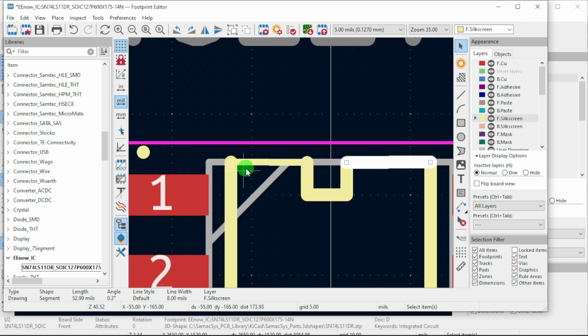Alright, so then I have a problem here with touching that. I would say make it 35. Let's see, 30 mils and 30 mils and 7. That looks, oh. Okay, so let's run DRC. Let's see if that's a problem. What's that? Warning.